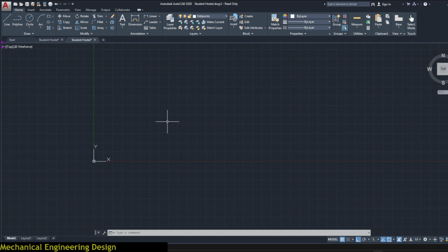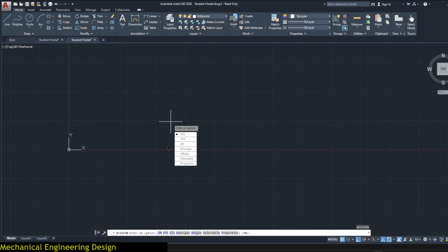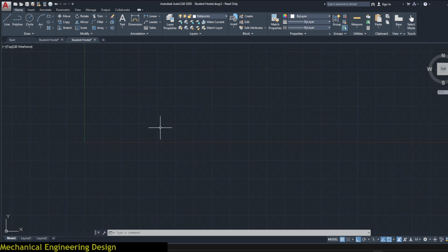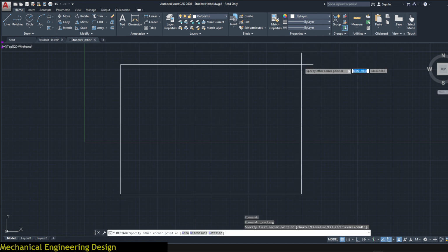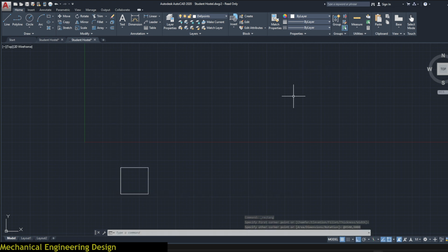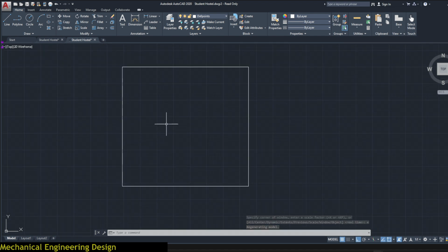The first thing I normally do is to move this UCS icon into its place here. So just type UCS icon, this one, and then select no origin. And it will be fixed here. The second thing, just proceed to draw. We'll use a rectangle, identify any point and drag it outside. Now, overall length is 9,500. We are using millimeters as units. That's metric units. Then press tab and the height of 9,000. Press Z, enter, and then E, enter to zoom extents for this drawing to fit the screen.